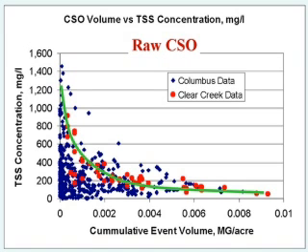When you look at a disinfectant, you look at a dose-kill relationship. This graph shows raw CSO, different samples dosed with different doses and of different qualities. If you just look at the fecal coliform in the effluent from a test against the dose, you'll get a big scatter, and it's really hard to show anything. But if you normalize the dose data by the quality of the water, like, for example, TSS or BOD or COD, you'll start to see a trend or a regression equation that makes sense. And temperature is another parameter you need to consider if you're doing these dose-kill relationships. So if you divide the dose by, for example, the level of TSS, and then by temperature, you'll get a better and better equation to determine how you dose your CSO.